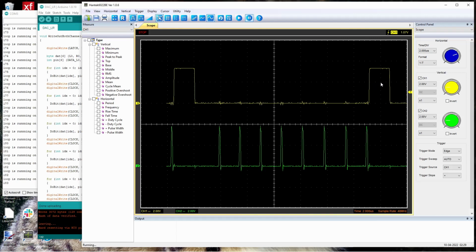So we probably have to call it 7. And it's actually closer to 8 before we get back to the falling edge of the latch at 2 microseconds per division. So that's 14, and that's not fast enough. Not for 96. It would work for 48.